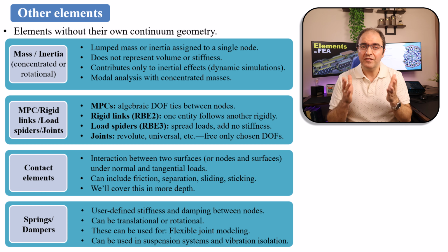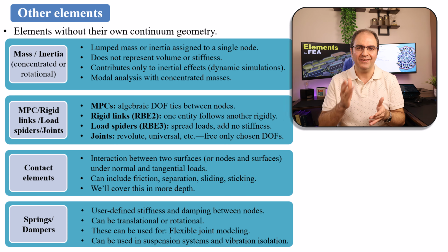Note that unlike solids or shells, these elements don't define their own volume of material. Instead, they act as connectors, constraints, or special interactions applied to surfaces or nodes of your existing mesh. Therefore, each one has its own set of inputs and settings.